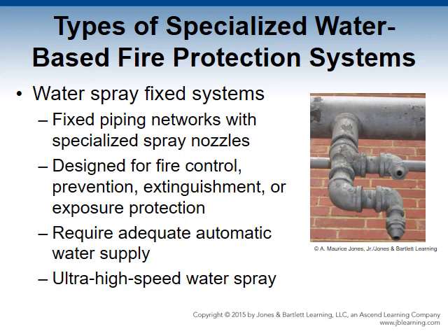The water spray fixed system components. They require at least one adequate automatic water supply that is connected to the deluge, pre-action, high-speed, and possibly an alarm check valve. Your activation can occur by heat, flame, or gas detection. It may also have a pilot sprinkler head or nozzles.